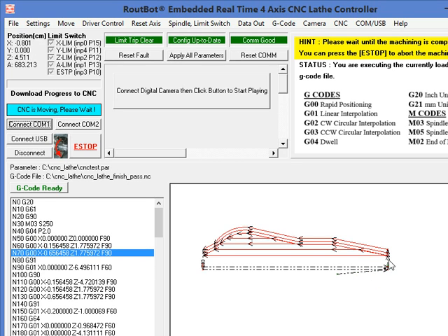Now that distance is the 0.5-inch clearance to material. The first pass, in this case, is not on the material, it is a little bit above. It's because of the way we define this. It could not be above because we define 2 finish passes and roughing pass and all that. The final result gives us 1 pass that is slightly above the material, but all the other passes will be on the material. So now it goes back.